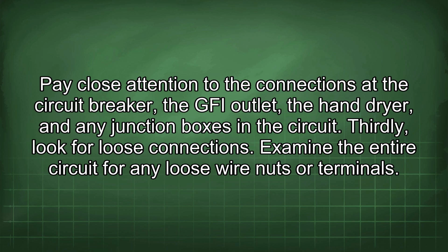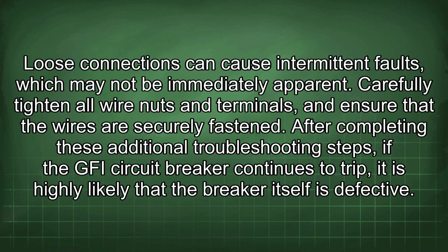Thirdly, look for loose connections. Examine the entire circuit for any loose wire nuts or terminals. Loose connections can cause intermittent faults, which may not be immediately apparent. Carefully tighten all wire nuts and terminals and ensure that the wires are securely fastened.